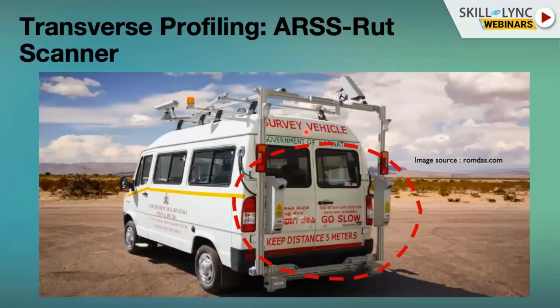And we have another set of lasers called transverse rut scanners. These will capture the transverse profile of the road. So the transverse profile basically gives you the rutting parameter, like rutting depth. What is the depth of my rut?